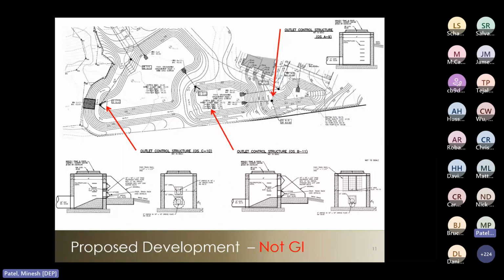These contributory drainage areas would most likely be larger than the ones that you would find in Table 5-1. They would then be more suited for those in Table 5-2, which would require a variance before they can be used for quality and recharge. Waivers are for the enlargement of an existing public roadway or railroad, or the construction or expansion of a public pedestrian access, which this project is not. So the next slide here, we're going to revisit variances a little bit.